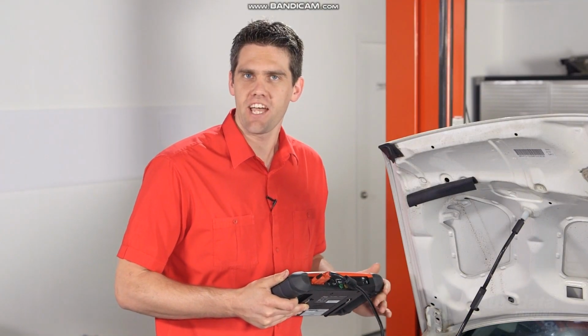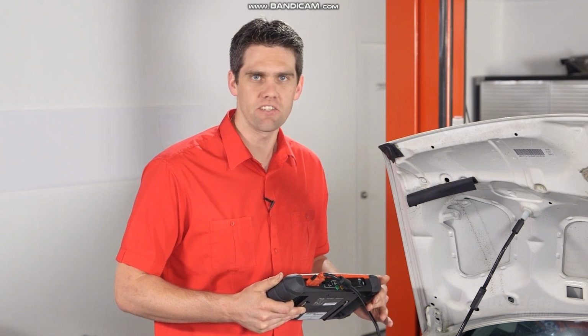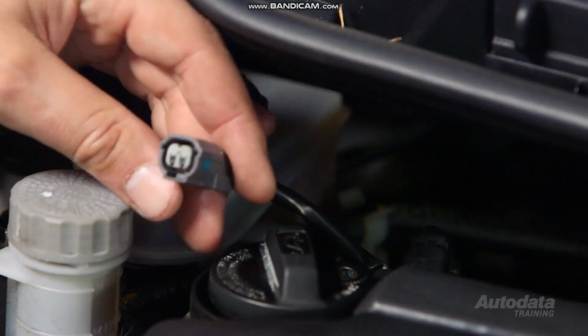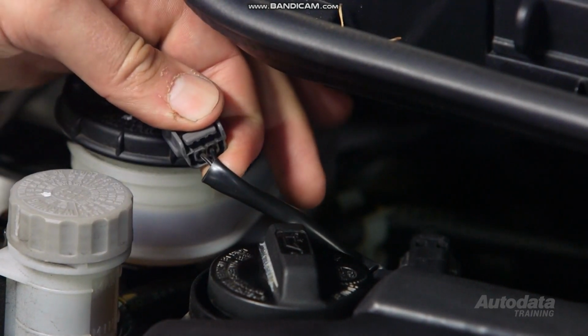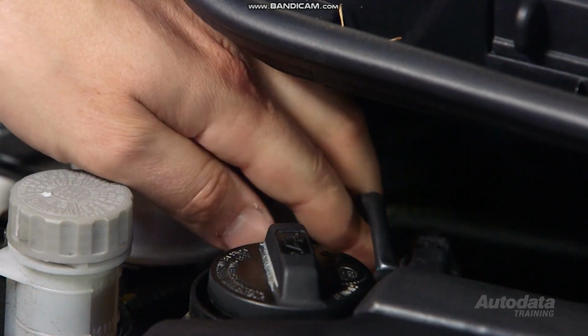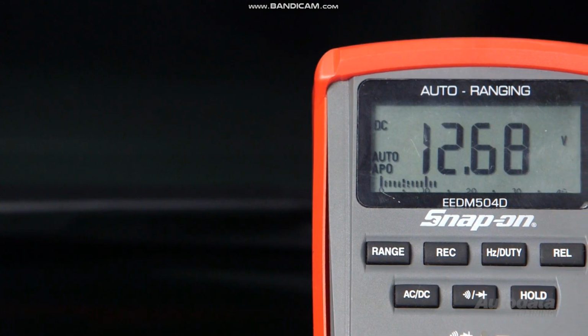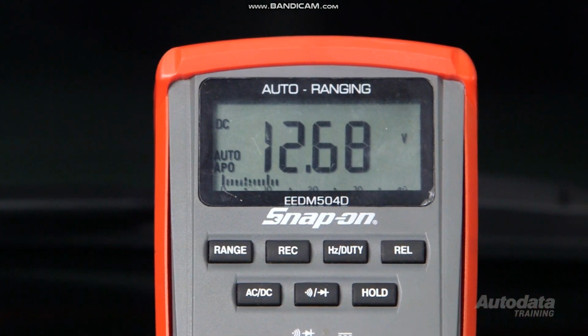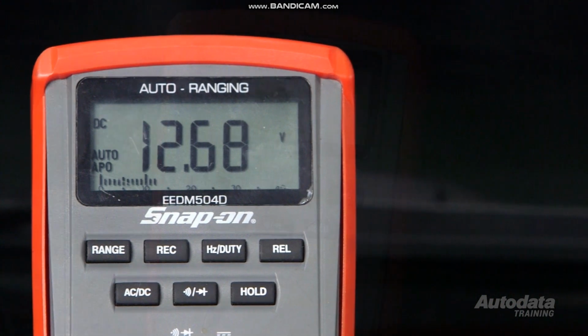If the readings change, the fault could be in the harness or the connector. Check for corrosion and any evidence of abrasions or damaged wires on the sensor. If this is all okay, move on to checking the signal circuit. Check battery voltage before testing the circuit. This is to give you a reference voltage for all of your readings.